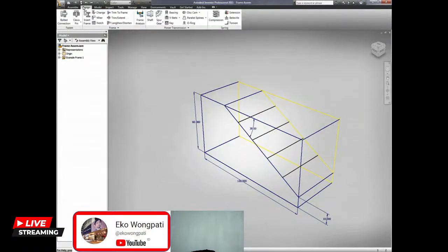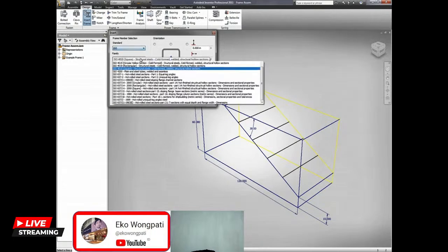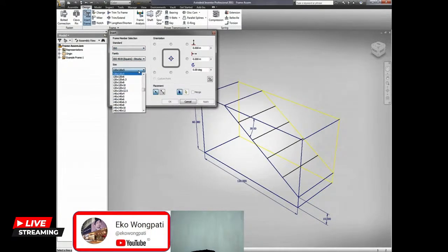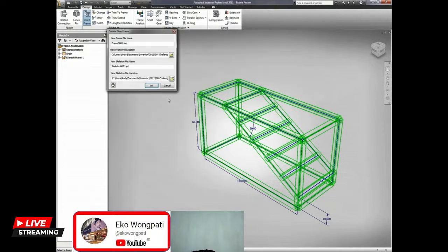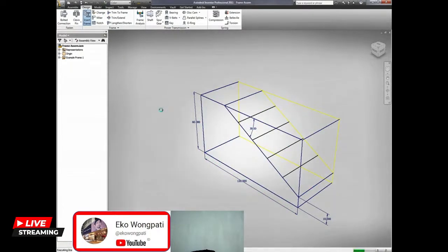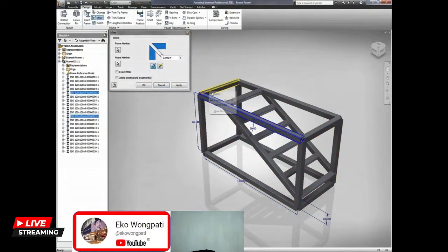Okay, so what we're going to be doing in this example is taking a look at Inventor 2011, making use of the frame generator for structural member design or static frame member design. Now, the first thing we're going to do is make use, inside of Inventor 2011, of the hundreds of thousands of different components inside our library to make use of all these different profiles. We don't have to manually create these different frame structures. Rather, we can use an existing sketch and extrude all those different profiles along all the different sketch lines instantaneously.